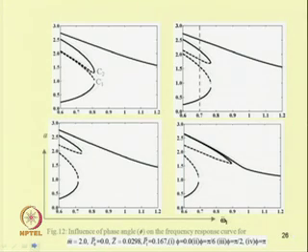next one can study the case when the system is excited at a frequency which is near to both omega 1 and omega 2. So, if it is near to both, that means when it is subjected to simultaneous principal parametric and simple resonance case, one can observe the response of the system like this.